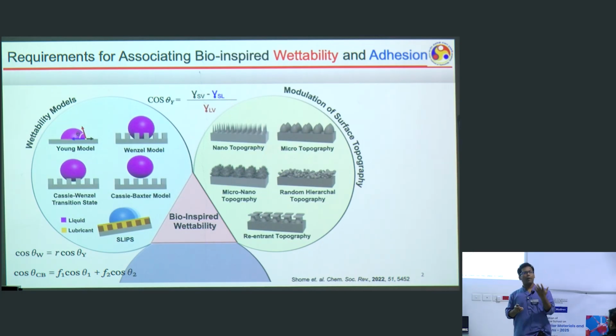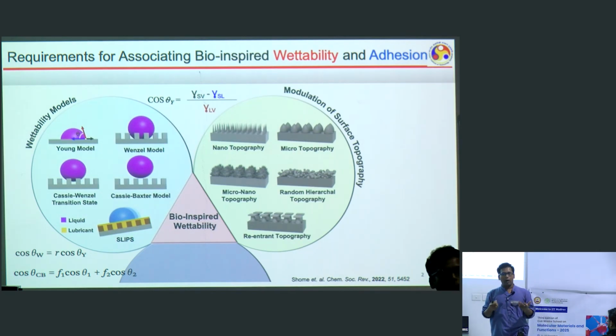But you might want control over the adhesion of that water droplet for some other purpose, but not at the cost of compromised wettability. The interface continues to display superhydrophobicity, but you want it to allow the droplet to roll only at a higher tilting angle, so that you have more control over the rolling of the droplet, with no loss during transfer of the droplet from one place to another. That basically gives more freedom in terms of open microfluidics. That is another segment. So how can we achieve it?